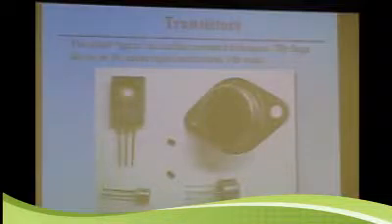If you want to see what some transistors can look like, small specks on the surface, they're actually surface mount transistors. These are like power transistors. This one in the upper right can dissipate 100 watts. This is a little bit smaller, but you'll see the hole here. What you generally will have bolted on there is a little metal frame that is essentially a heat sink. It allows the heat to dissipate from the transistor and get rid of the heat, because heat is the enemy. In general, heat's the enemy of electronics. So whatever you can do to get the heat away is worth doing.